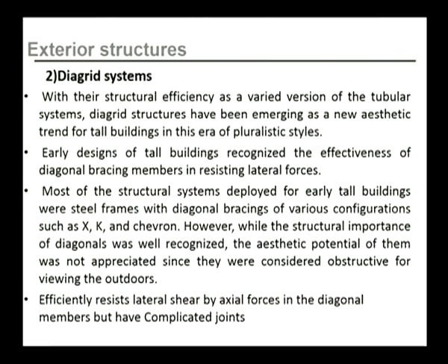However, while the structural importance of diagonals was well recognized, the aesthetic potential of them was not appreciated, since they were considered obstructive for viewing the outdoors. This kind of system efficiently resists lateral shear by axial forces in the diagonal members but has complicated joints.